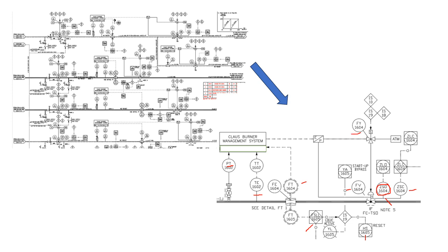FY normally stands for the actuator, flow actuator. E and P stand for electric to pneumatic converter. This YL symbol with these marks normally indicates some light. FC is flow fail close and TSO stands for tight shutoff. So as you see more and more P&IDs and try to interpret them with respect to my previous table, you get to know more and more.